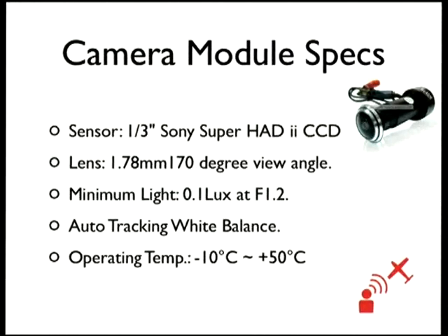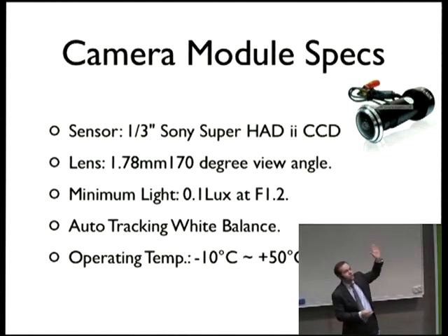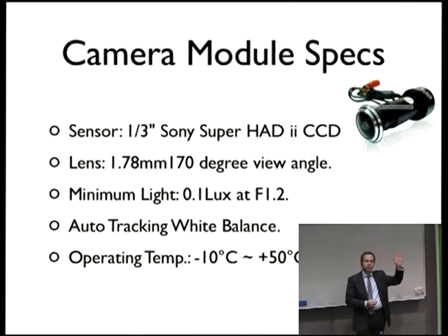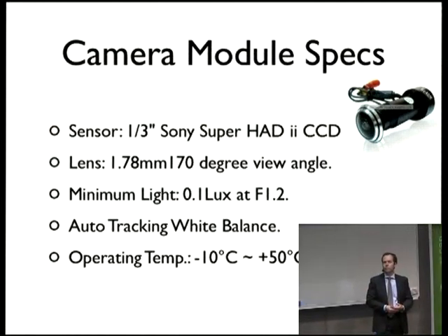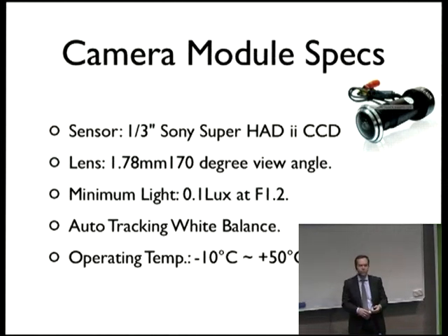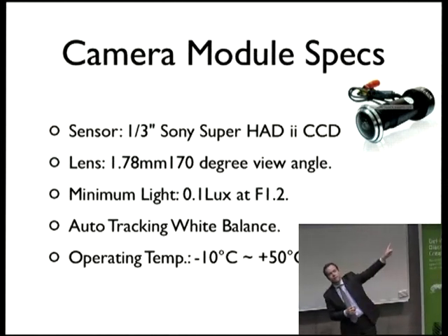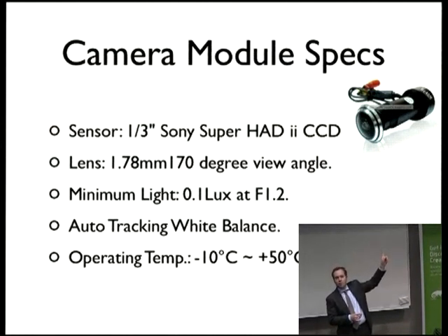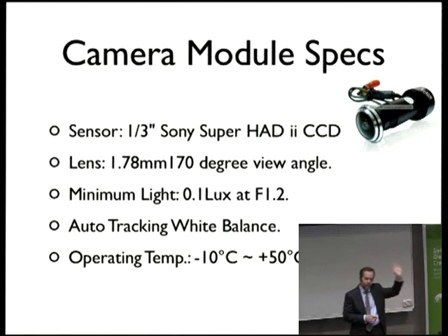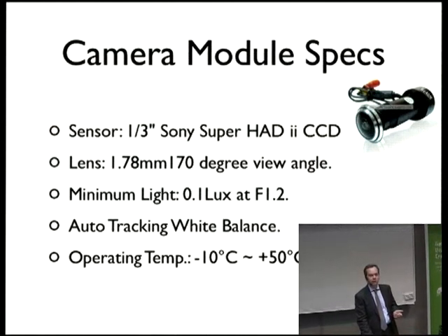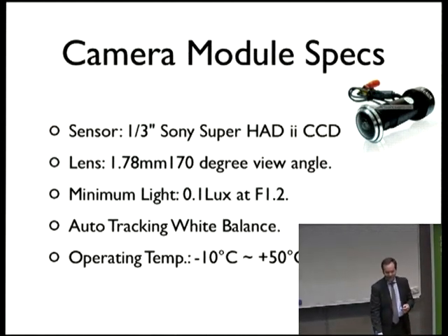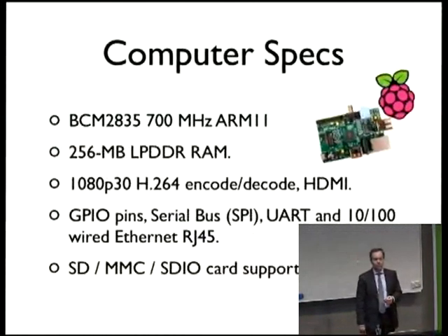The camera spec, I mentioned it's a door camera from China with the lens and the build, and the sensor is from Sony. It's a very simple camera, but you'll notice on the specs, it's extremely capable. I mean, f1.2, it can operate in pretty low light indeed. It's got resolution which is just above television, so we can get everything we need for the OpenCV to recognize things like people and roads. And it is able to take a lot of temperature variance. So when you're storing it and so on, you needn't worry that you're going to lose resolution on the camera because the lens will fog up or whatever. It's a very versatile solution, and like I say, it only costs $41 off AliExpress.com. That's where we got it. Very cool technology, just a door camera that was overbuilt.